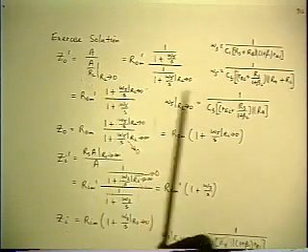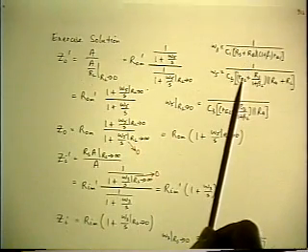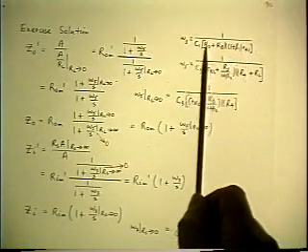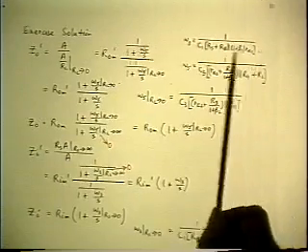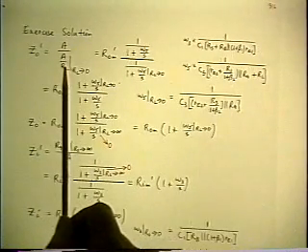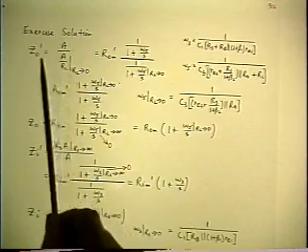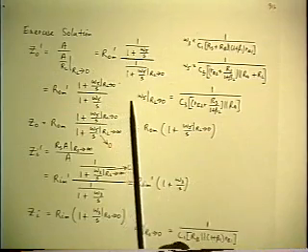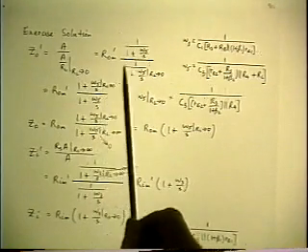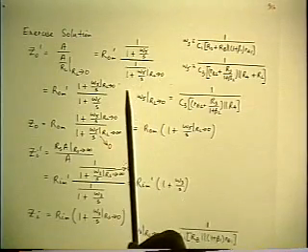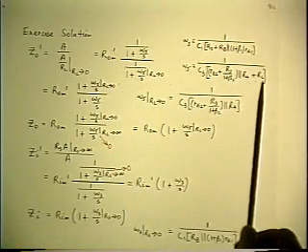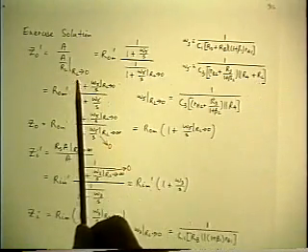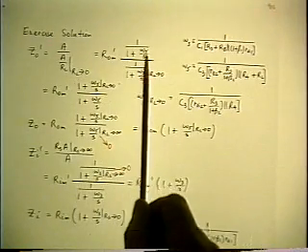And the first thing we do is look into the two corner frequencies and see if RL is contained inside them. And when you look inside the omega 3, you find there is no RL in it. So the omega 3 corner will cancel out from the two positions where A exists. So you don't even need to write it. Previously I've been writing it in and then putting a line through it to cancel it. But now when you get used to that idea, you don't have to write it in the first place. You just leave it out. When you look at omega 5, you find it does have RL in it. So it will be affected by the limit, and it won't cancel out, and so you have to retain it.